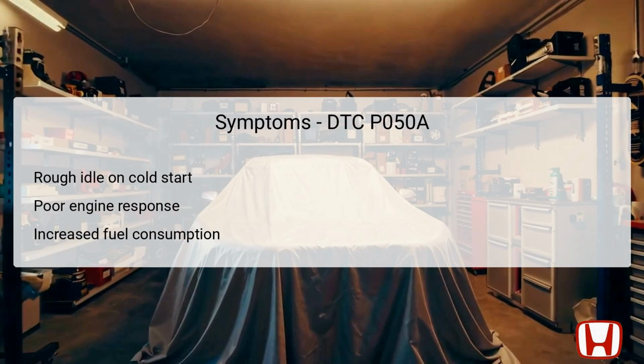The symptoms associated with DTC P050A typically manifest as noticeable engine performance issues. One of the most common symptoms is a rough idle when starting the engine from a cold state. This can be particularly disruptive and may lead to a lack of smoothness during initial acceleration.